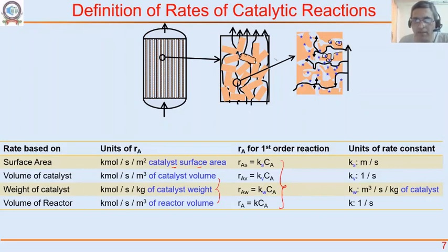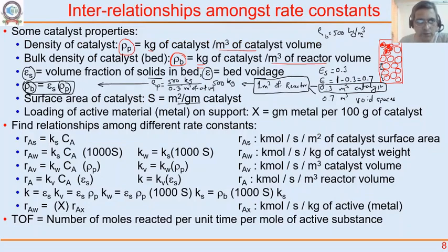It is the external plus the internal pore surface area, like this. And you will see that the pore surface area is much larger than the external surface area, right? So we need to define how much surface area is there per unit weight of catalyst. Typically it is defined in terms of meter square per gram of the catalyst.